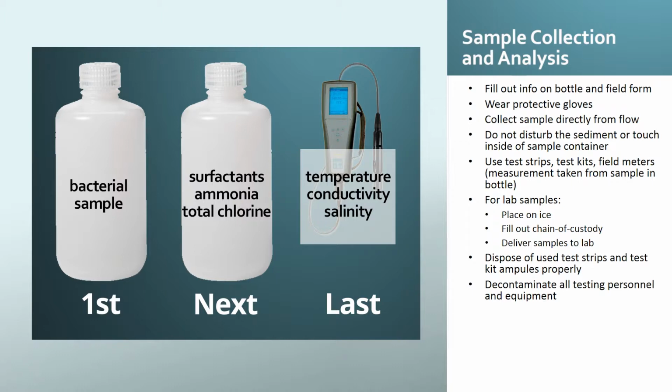Based on experience of the PVPC's Chicopee River Source Tracking Project, PVPC recommends surfactant analysis not be done in the field and instead be done by a lab or in a location with a hooded vent, only if the E. coli sample is shown to exceed the standard. This will avoid generation of excessive hazardous waste and human exposure to propanol, chloroform, and sulfuric acid.